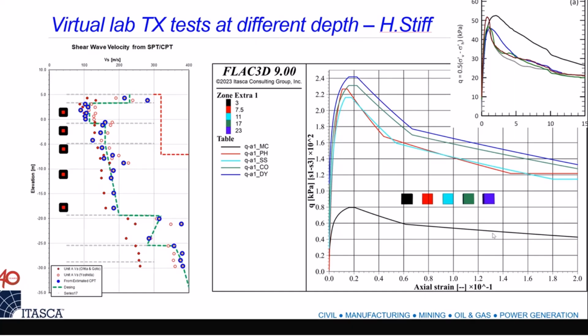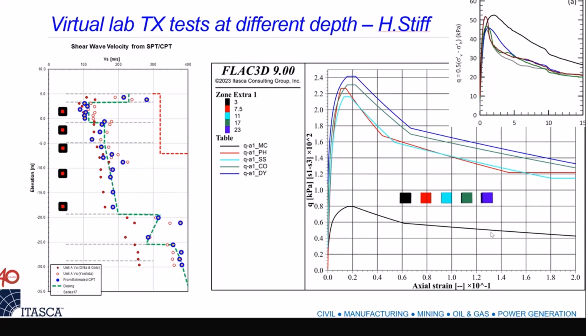We tend to characterize the Mohr-Coulomb model with just cohesion and friction angle, so sort of a linear envelope. But the effect of the nonlinear strength envelope, I would say, in any type of soil, some more, some less, is critical. It is crucial to have a better understanding of the mobilization of the shear strength, the volume of the soil that is pushing against our structure, and so the overall performance and behavior of the system.